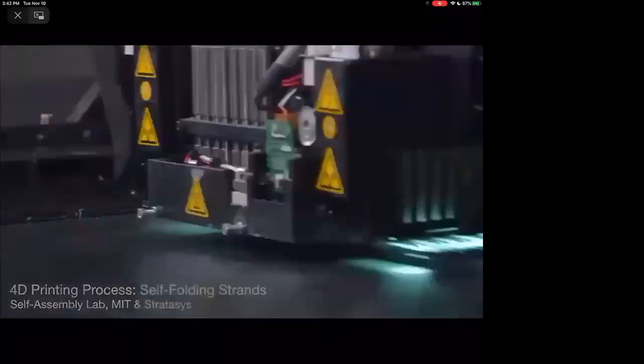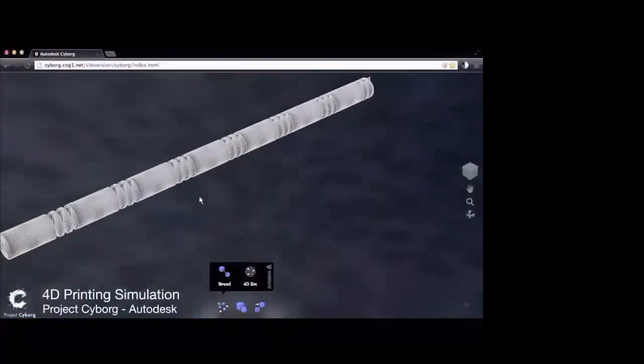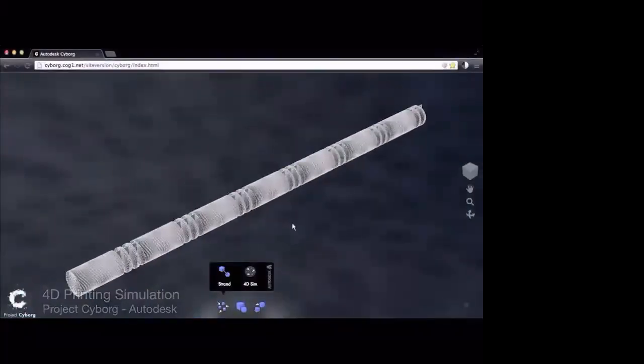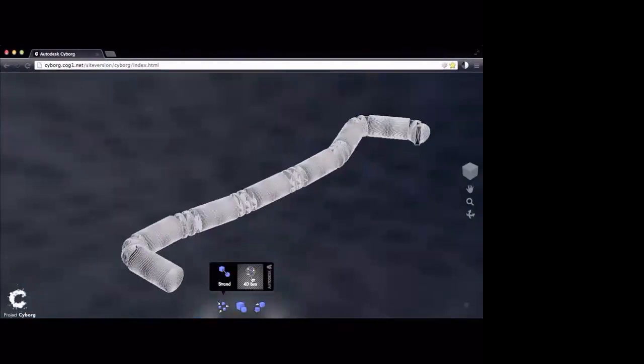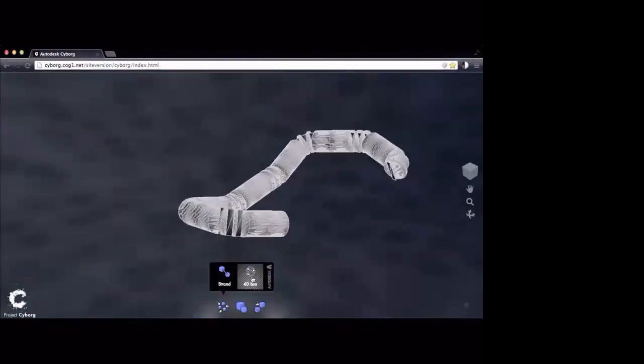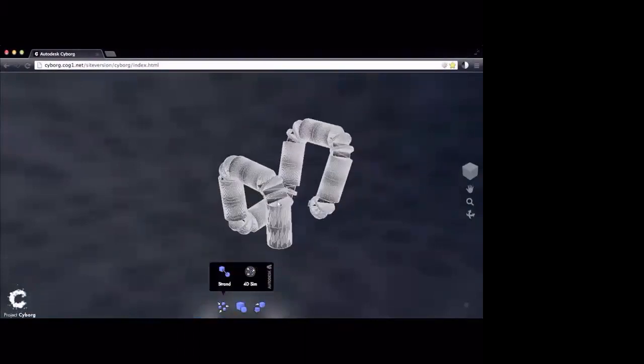See the UV polymerization, all that stuff about polyjet printing. Sorry for the flashing lights here. It'll be over in a sec. Okay, so they can also do a simulation for this. So if they know the material construction, they can do a deformation simulation in order to get the type of folding or the type of 4D behavior that they want.